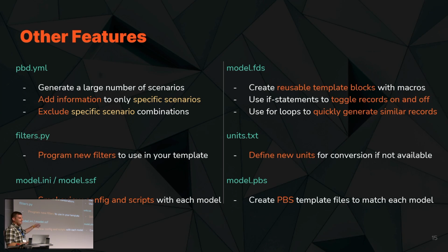If you know how to write the SSF script file, and it's all documented in the SmokeView user guide, you can make it faster using this template system and also put it in that folder directly. It will have the same name, which is what SmokeView is going to look for. And it's just there, so you could batch run all your SmokeView scripts.